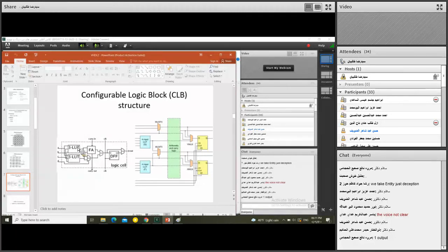Then here we have a memory with 3 address lines and 8 cells for the memory, and 1 output. Then this memory can implement each logic function with 3 inputs, as a lookup table with 3 inputs. Thus we can implement each logic function by these lookup tables.